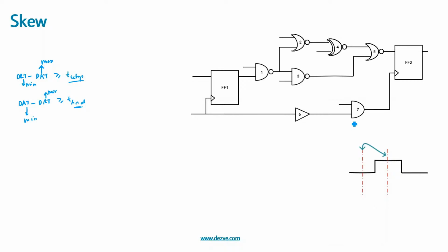Now the clock skew can be okay. So there can be a circuit like this as well. It's not necessary that the destination path will have a skew. So this clock network can come here, this can come here, this can have different buffers, and this can have different buffers as well, correct? So this path can have less skew, this path can have more skew, vice versa, correct?